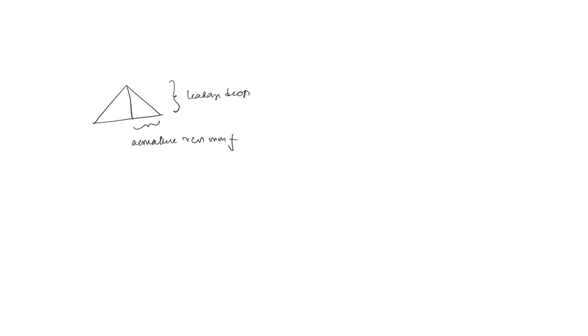We will start from the equivalent circuit of the synchronous machine. The equivalent circuit consists of a voltage source in series with resistance and inductance. The voltage that is available here is the terminal voltage, this is the armature resistance, and we have the synchronous impedance, and this is the generated voltage. In this inductance we are considering the leakage drop as well as the armature reaction. But we will make a slight modification and some assumptions as well.